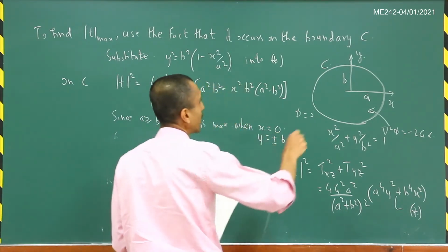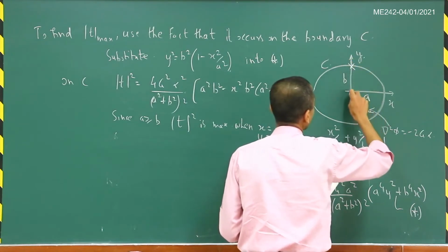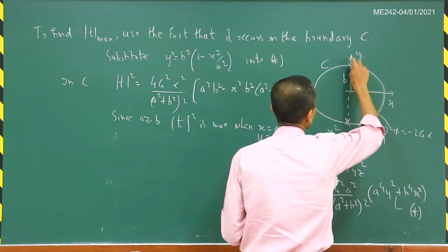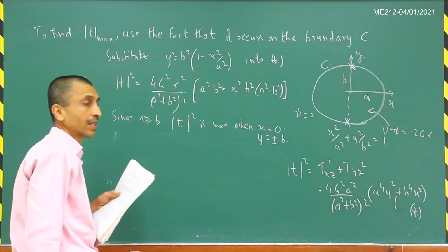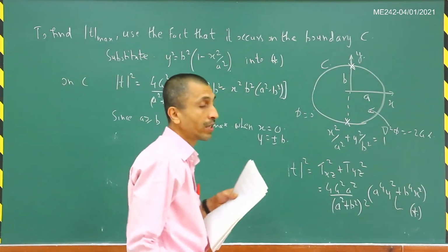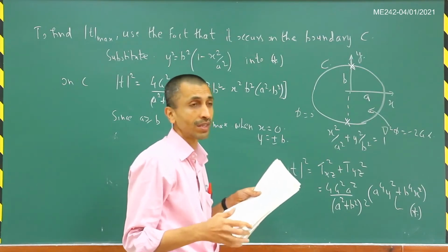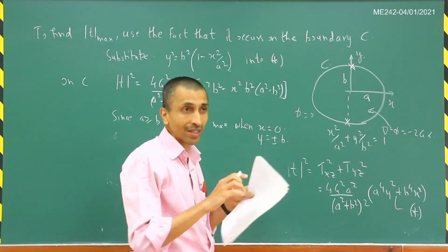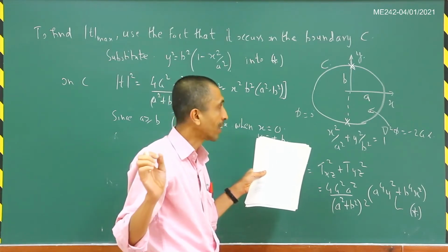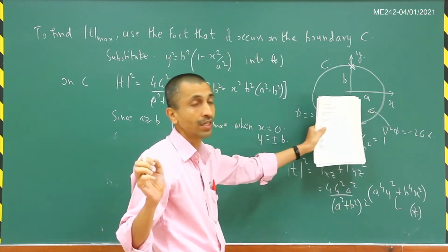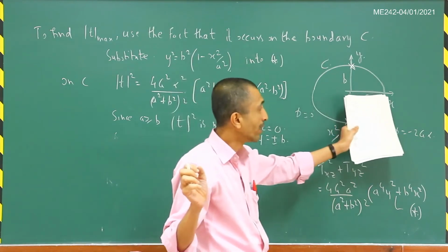If you draw this, these are the points where the maximum shear stress occurs. And this is something I mentioned in the last class, that according to our intuition we may think that the farther away you go from the axis of torsion, the more will be the shear stress.